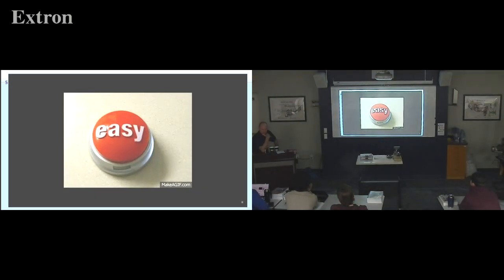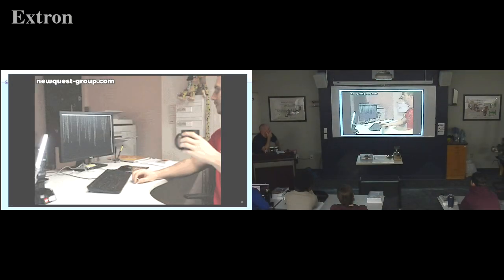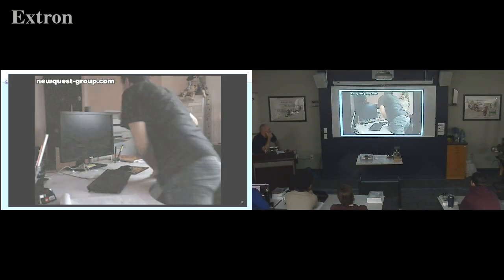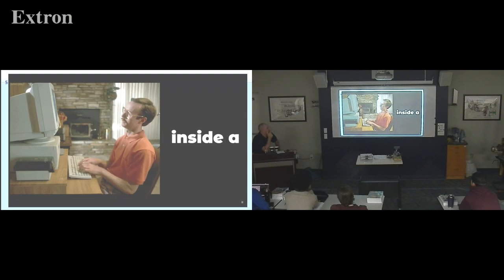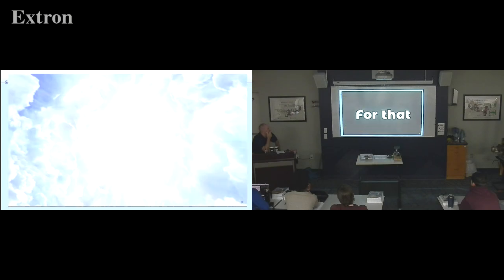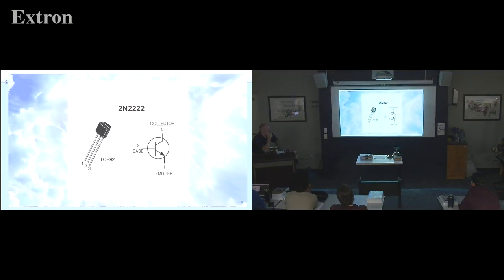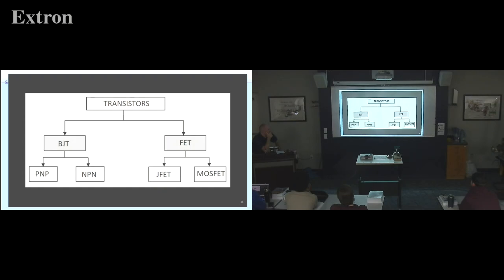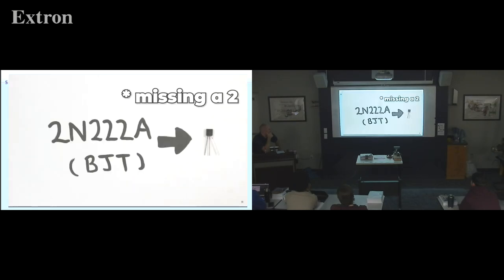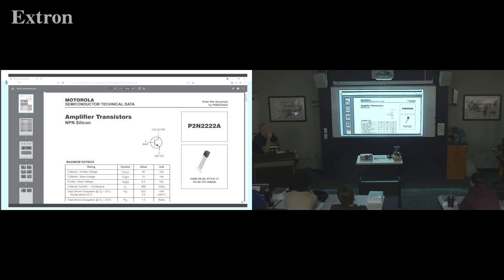I know these concepts are straightforward and we are just turning switches on and off with our hands. But how does this happen inside the computer? For that, we use the almighty transistor. There are many different kinds, but they all work on the same principle. Here we have the 2N2222 transistor, a common NPN BJT used for general purpose low power amplifying or switching applications.